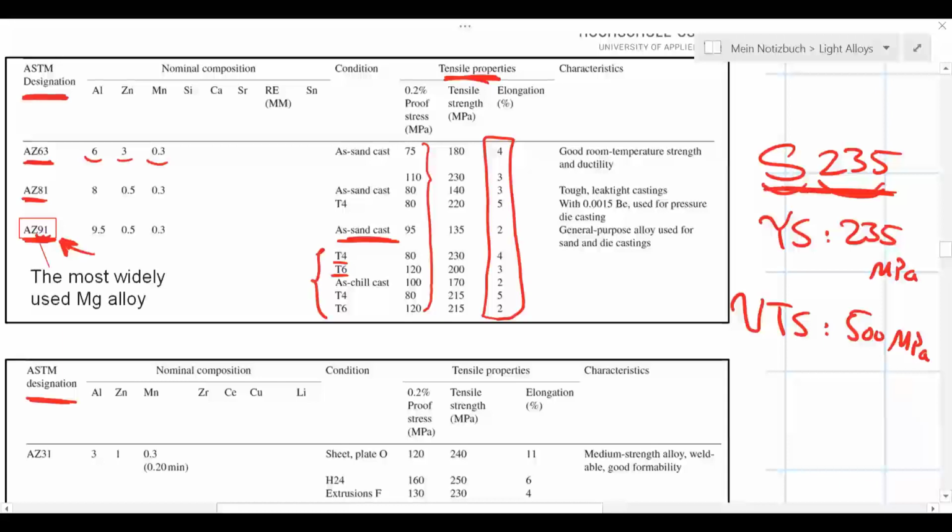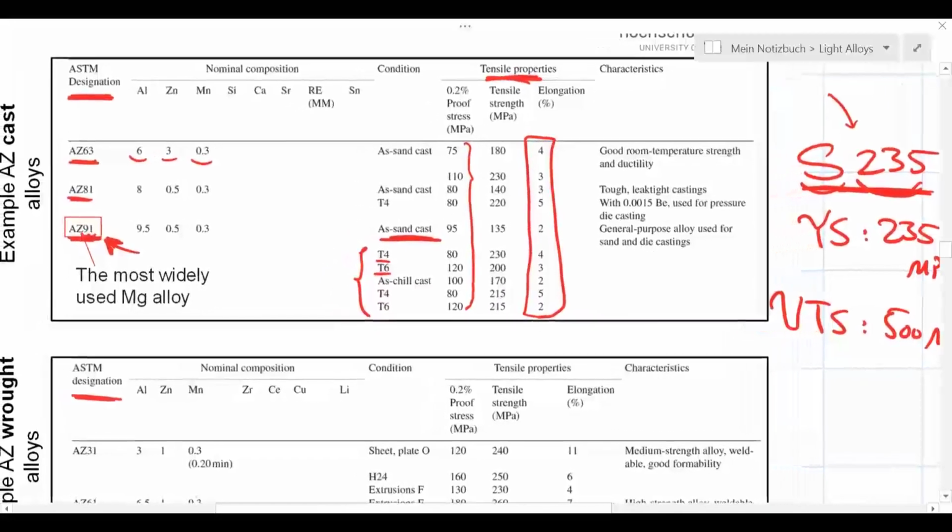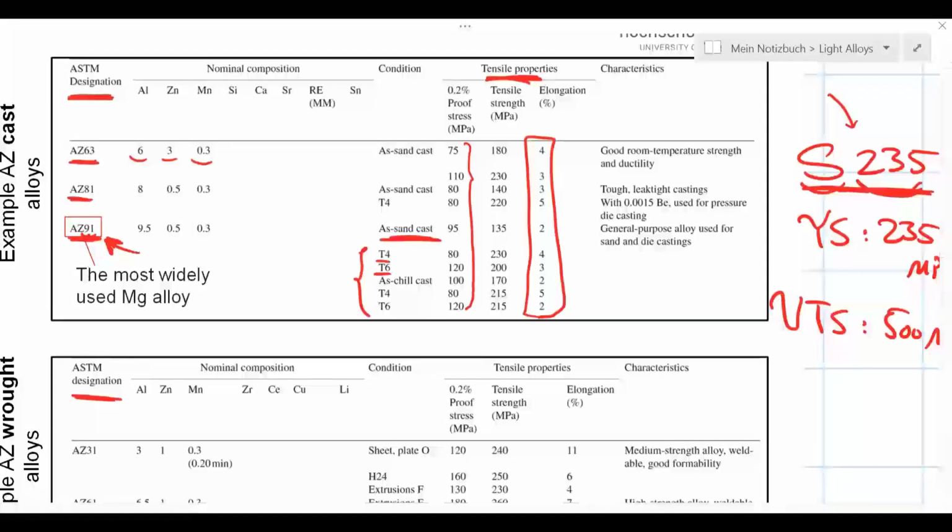They offer a higher strength and also a higher ductility. As I said, with a grade like this, you could expect 20% of elongation with a ferritic steel. And if it's an austenitic steel, you could aim for 50, 60, 70% of elongation, much higher ductilities.